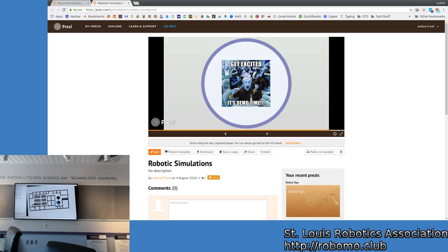So during the launch process, I actually launched everything at once, but you can launch Gazebo as one process, and then you launch your robots, all your robot's code, as another process, and then you launch RViz as another one to monitor all of that. So this is just one working demo of how it might be. And then they have some interesting plug-in feedback, like humans have RFID tags on them in this simulation, so your robot can actually read which human it's next to, if it's driving around looking for somebody.